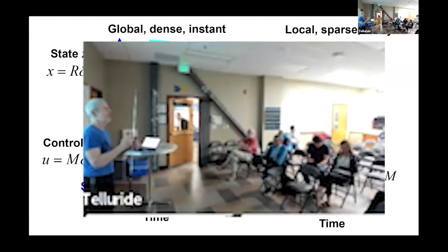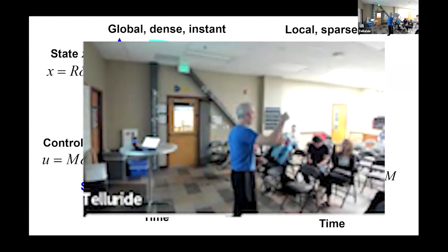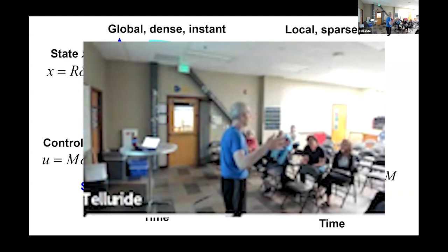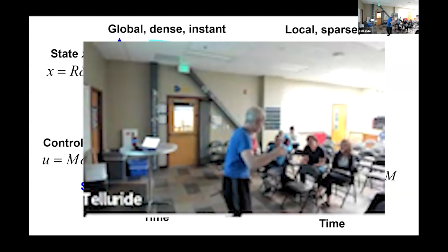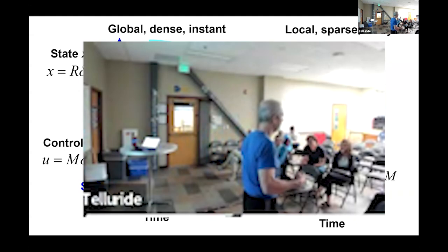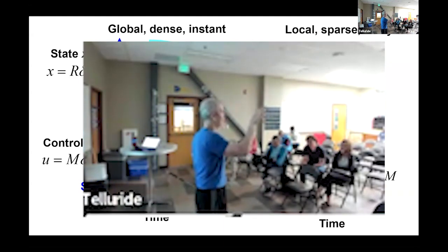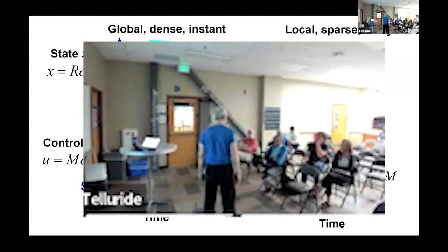As a consequence, you can run algorithms you would never run before. You can start doing MPC-like things because your state space is so much smaller. You can do this MPC on much richer models than you could have done for the whole thing. So there is one advantage if you just care about nonlinearity: all the tricks we have to deal with nonlinear systems are expensive. They're expensive offline to compute the controllers, and the actual computation online of MPC for highly nonlinear systems is very expensive. This cuts down the size of the state space because you're doing everything in patches. So it does have that benefit, but it doesn't fundamentally change what you do in a patch. It just makes it small. So I should have been clear about that. Yeah. All right. So, anyway, thanks.